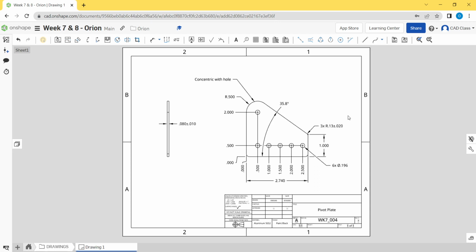A lot of you that were on the team last year will remember a process that we would do pretty frequently if we had bearing holes in a part, whether it was polycarb or aluminum on the router. We would stop the router and have it do the holes for the bearings, and then we would move the head out of the way, test fit the bearings into the holes on the sheet, and then if they were not quite right, we would go in and adjust the program and rerun the profiles, and it would recut the holes. We were basically checking the tolerance of that hole by using the bearing to test fit the hole.